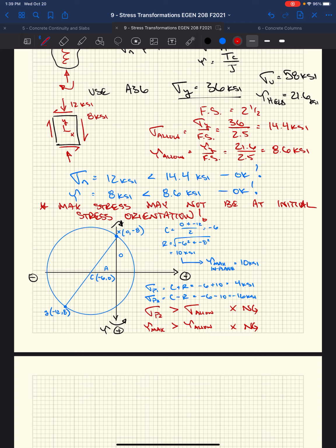Fortunately, it's unfortunate but fortunate, factors of safety have saved more lives than we'll ever know, right? Because originally, this really doesn't yield till 36. And so when we're saying our normal stress is 16 KSI, we're still less than half of our yield stress of our material.